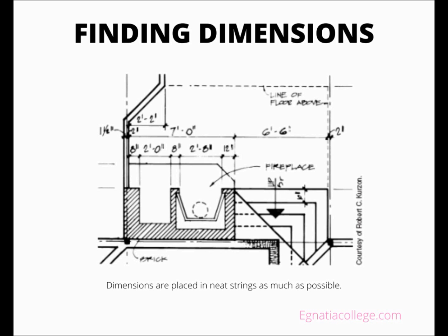place. Commercial buildings may require a thicker wall, where the electrical service panel is flush mounted, and the panel box is deeper than the standard 3.5 inch wall. Many times, this thicker wall requirement is not shown on the floor plan or drawing details. The utilities that are to be stubbed up from a concrete floor slab into a wall are installed prior to floor slab concrete placement and, therefore, prior to the wall locations being determined by the framing contractor. The utility installer must be able to accurately predetermine the specific wall locations.